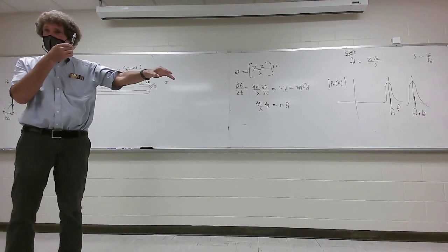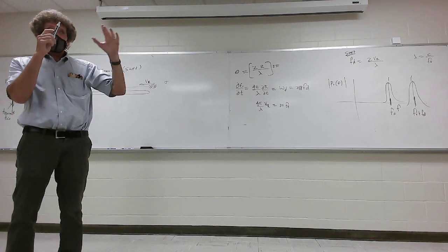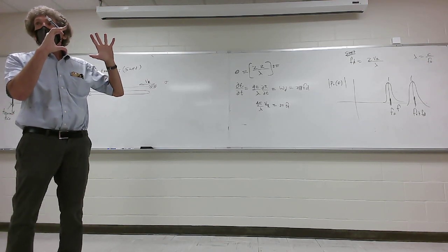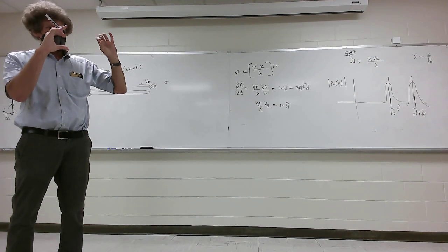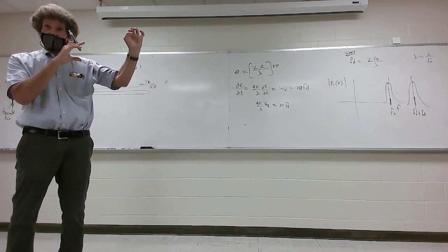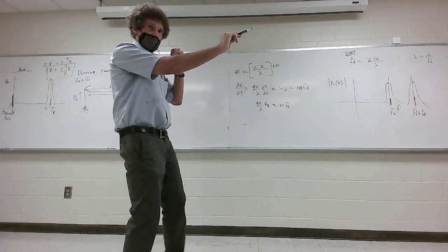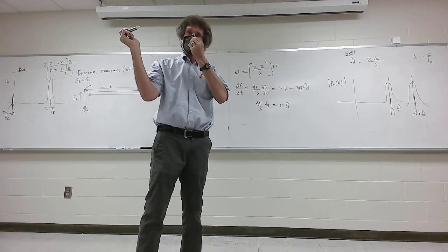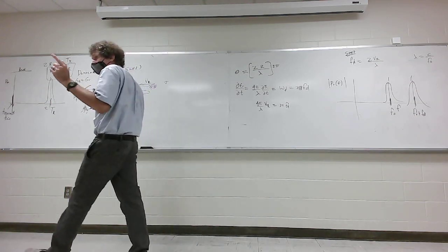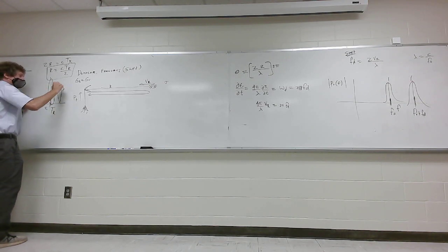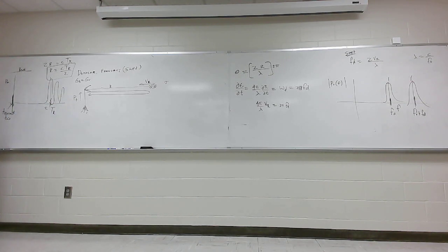It's called ground bounce. If I have a target out there and I've got a radar here, the gain of most antennas isn't a pinpoint spotlight gain. It doesn't contain all the signal. So you'll get some of the signal hit the ground and reflect back. In the real world, you'll get something like this. You'll get that, then you get this, and you might get a fourth one where it hits the target, then bounces back into the ground.